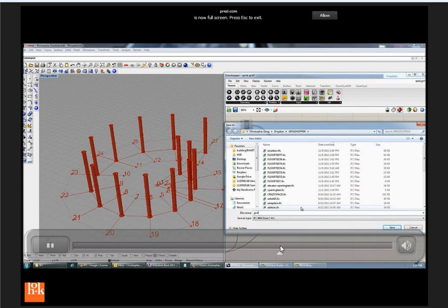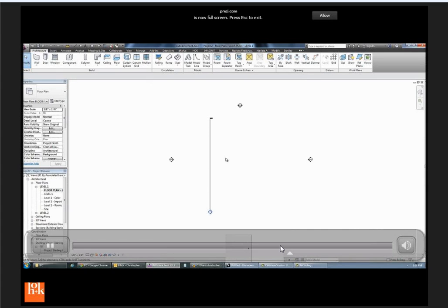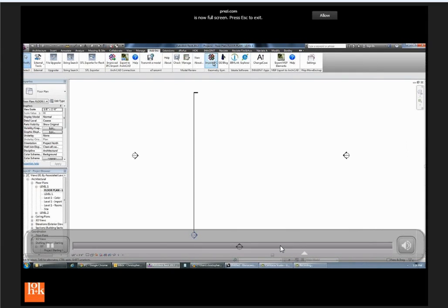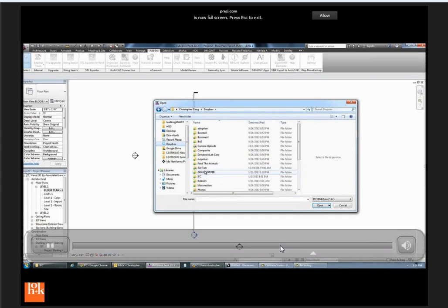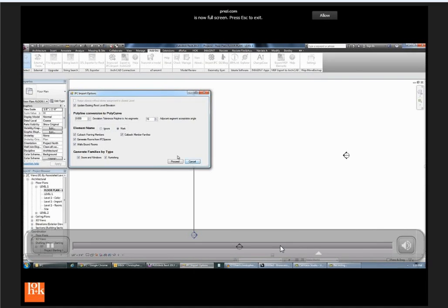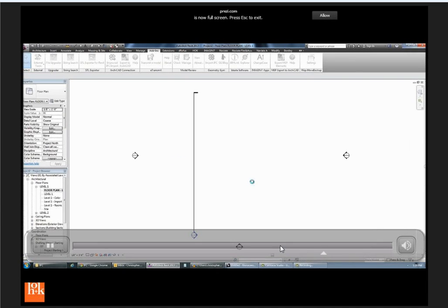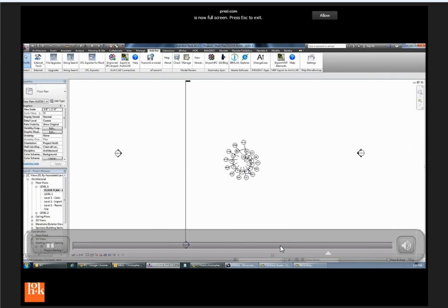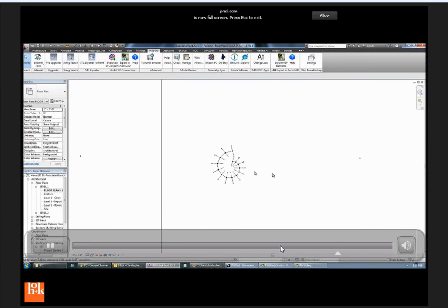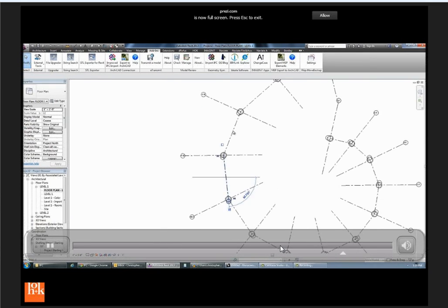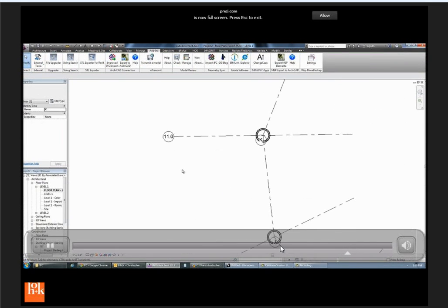What's interesting about this is that I originally developed this little script when we had Revit 2012. Now Revit 2013 allows for multi-point segment grids, which just weren't available, and I think they've opened that up in the API. But currently, when I bring this in, you're going to see... Whoa. You guys still see? Because I lost all my signal. There we go. Sorry, guys. So there you go. Grids 1 through 14 all came in, and connecting grids went around there. That would be pretty hard to do inside of Revit, to get those orientations correct and get those intersections exactly where you want them.